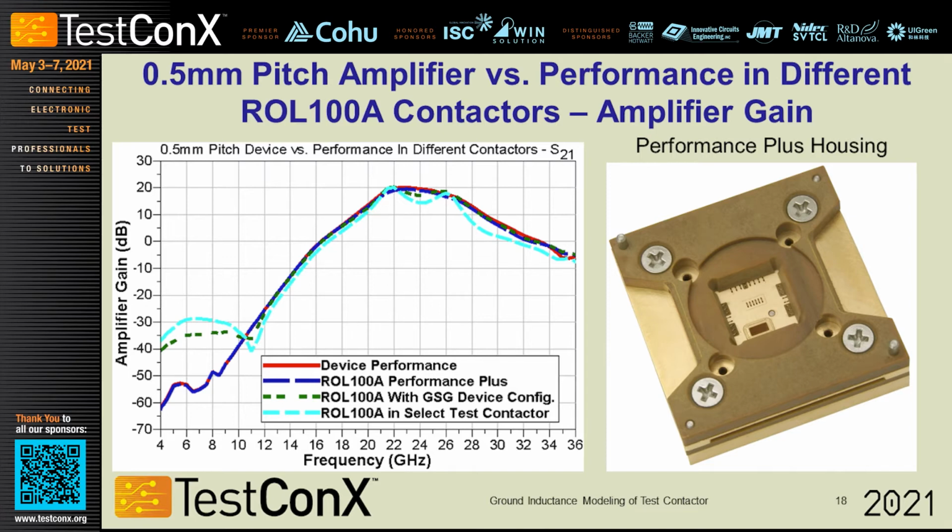And in this case, and this is not part of this design, the square opening on the bottom part of the inside of the contactor is a waveguide port. Typically, that's for a chip that has a waveguide port on the outside, or maybe even an OTA type, over-the-air type device, where it's an antenna radiating outside the chip.